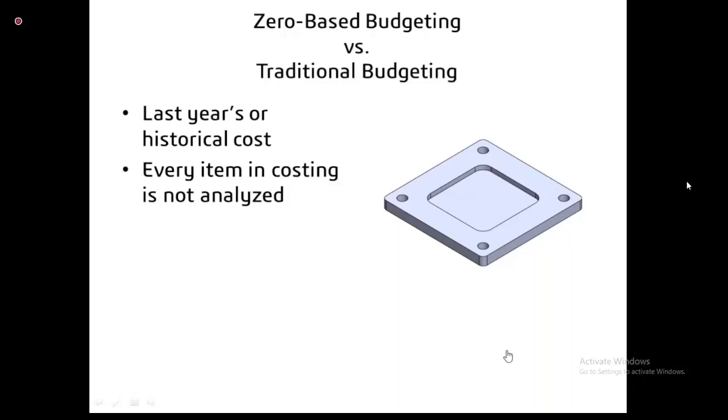We made changes in the type of the tool. Whatever slab milling or milling operation was used on this component, we made changes in tool type. Then we made changes in tool material, tool geometry, the manufacturing sequence of the component, and the tool path.